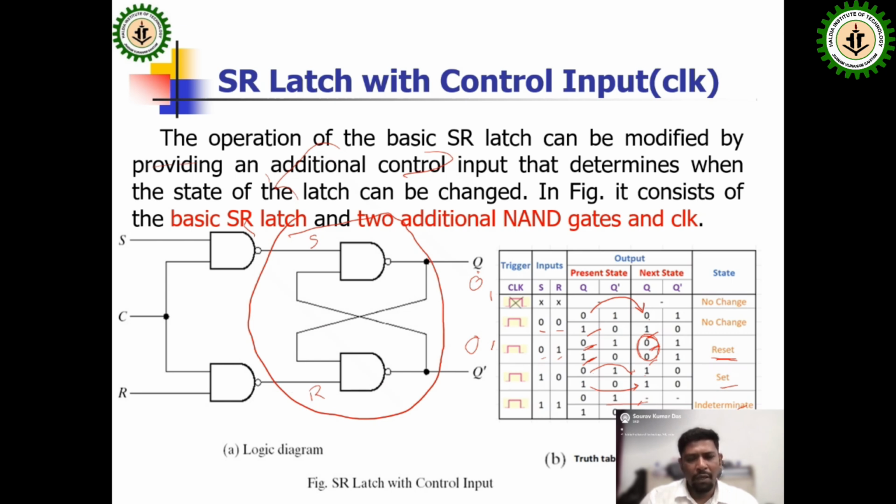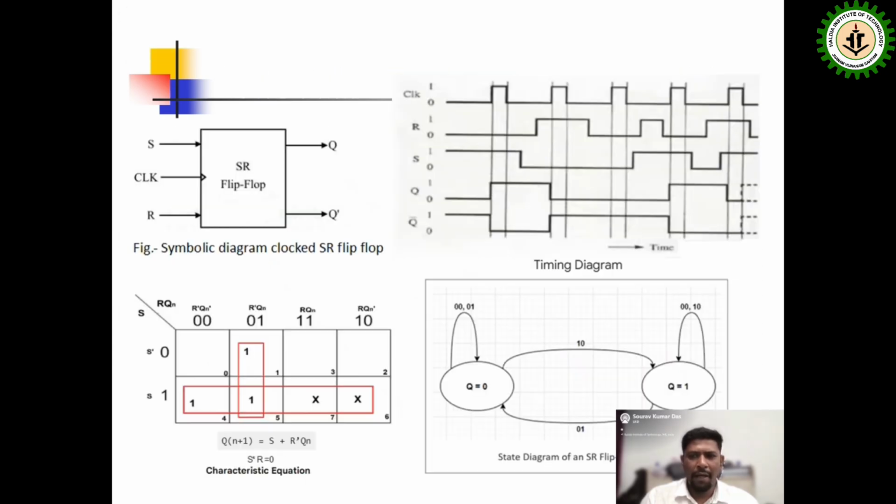That's why we build another flip-flop, the D flip-flop, which I will discuss later. But the SR flip-flop has some characteristics. This is the truth table, or characteristics table. Symbolically represented, this is the clock with a positive edge trigger. But for a negative edge trigger, in the clock position you write this negative edge, the negative clock.